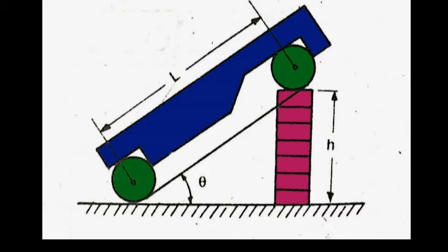Why do we not prefer to use a sine bar for measuring angles more than 45 degrees? Because the accuracy of the angle set by the sine bar depends upon the errors in its important dimensions, such as error in the distance between the roller centers, errors in the combination of slip gauges used for setting, and error in parallelism between the gauging surface and the plane of the roller axes, etc.